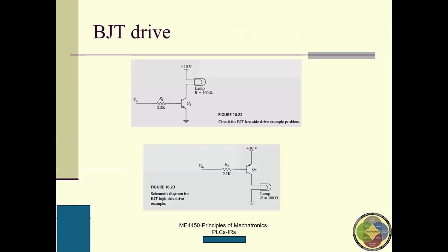No question? No question. This is the BJT drive. How it drives, how it works, I'm going to tell you. I'll go here, guys. This is 0, this is ground. So this is NPN, right? NPN. If this guy is high enough, and that means the voltage difference between these two terminals exceeds the threshold value, then I have current, then the light will be turned on. If this guy is very low, the light will be turned off. So this is a solid state switch.